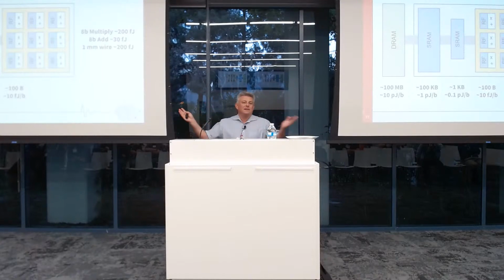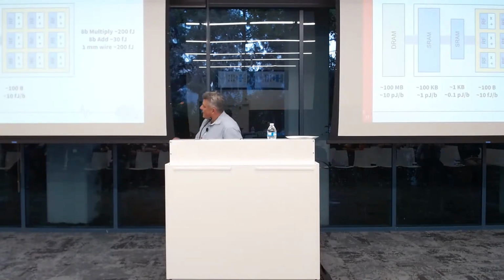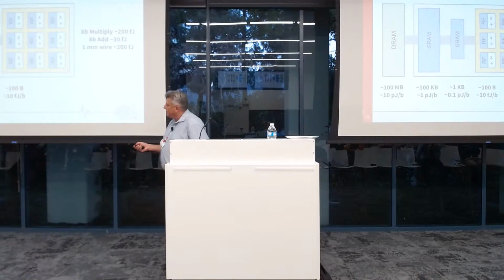And this is a completely non-trivial problem, right? This is actually really hard. So what I want to do now is get some asymptotes. So for example, how much energy would you actually expect this DRAM interface to contribute, and what efficiency asymptote does it lead to?